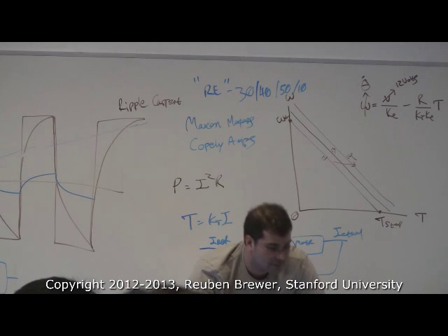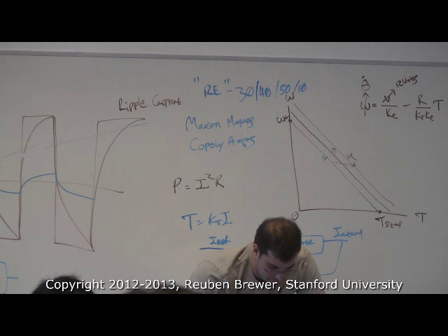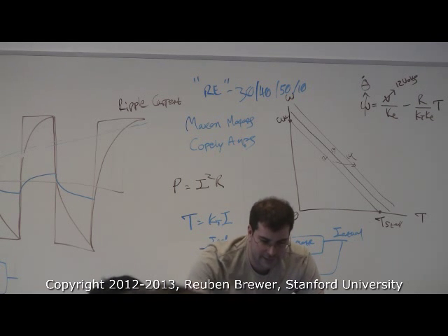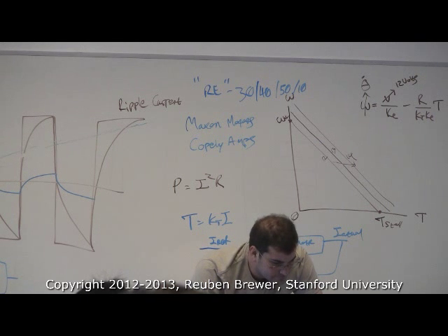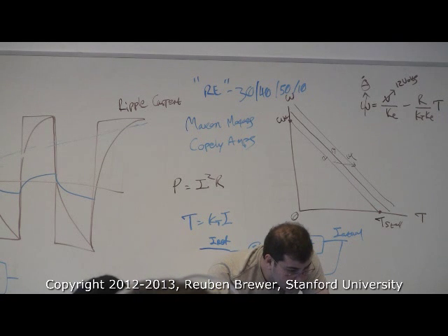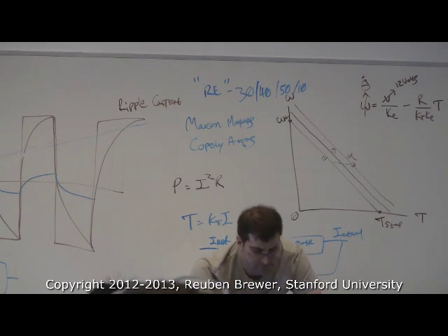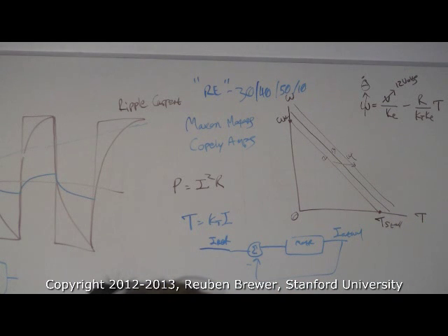Yeah. You want to say why PWM instead of a linear amp? I actually don't know. Feel free to explain though. Okay, so the reason you use PWM is because the power is always either all the way on or all the way off. So it's much more efficient. If you have a linear amp, like old style, you're trying to get half the voltage out, you're dissipating half your power in a big heat sink. So that's why amplifiers and power supplies have been made so small, but they're all pretty much PWM. Way more efficient.